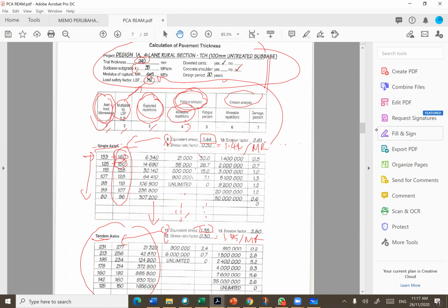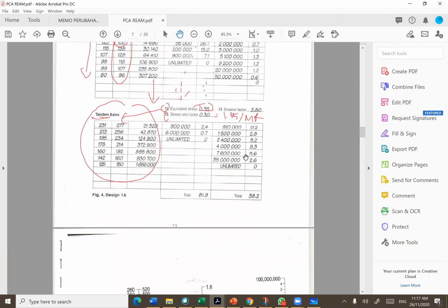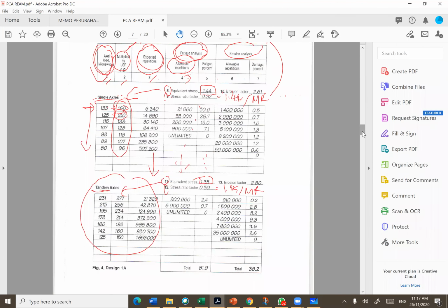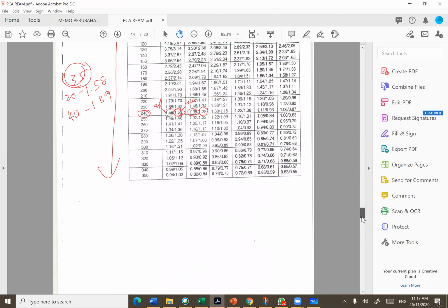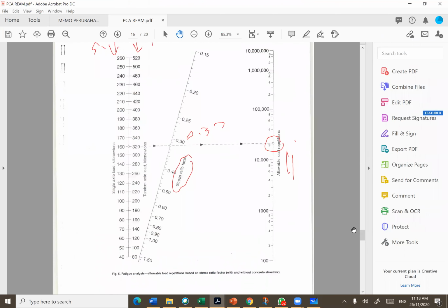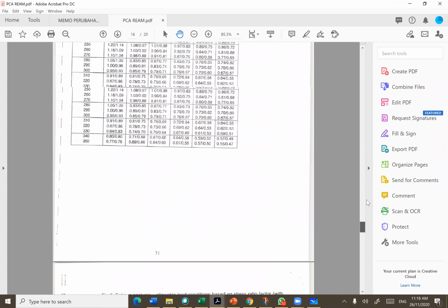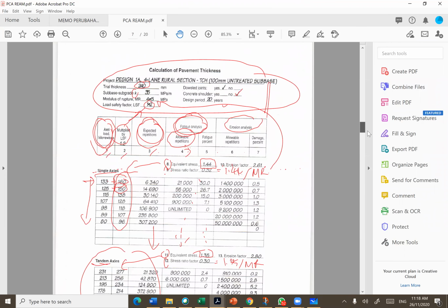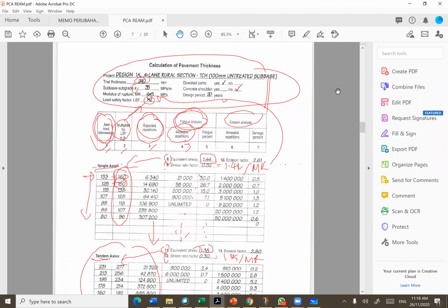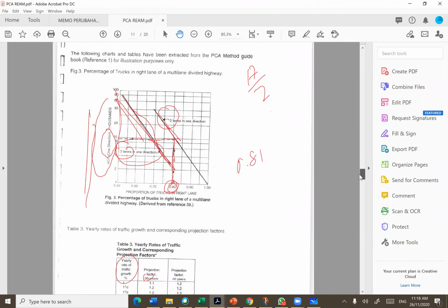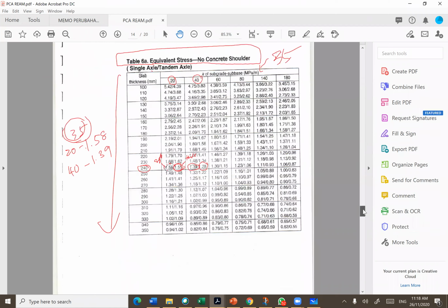Okay, so try and have a look at 150. Try on your graph on your paper, 150 with the equivalent stress and a stress ratio factor of 0.32. The same stress ratio factor, the same point. So at the same point here, 150, connect, draw a line to 0.32, extend and read the value here. You should get roughly 55,000. Okay, 57,000, estimated 50,000. Can you get the value?